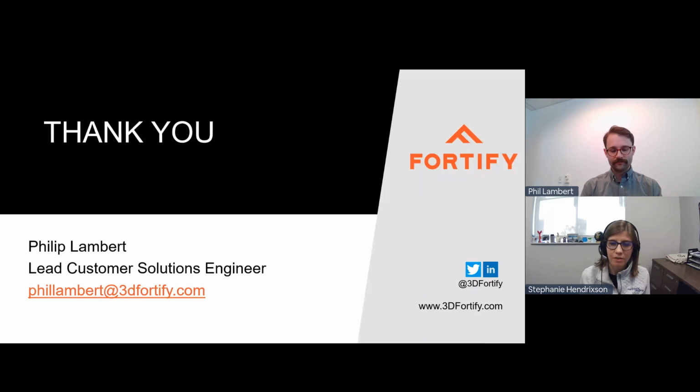Would there ever be a case where you would use Flux Developer and some of these tools in developing a non-filled resin, just a neat photopolymer? Sure, absolutely. All of these tool sets work just fine on neat systems, right? As my manager likes to say, at the end of the day, this is just a really, really good DLP printer. And so all of those tool sets, the slot working curve, the build plate adhesion, the rheology, all of those things can be leveraged to develop unfilled systems. It just turns out that the system's also designed to process filled systems as well. So that's where we see the value prop. If you want to do neat systems, it's available to you as well.